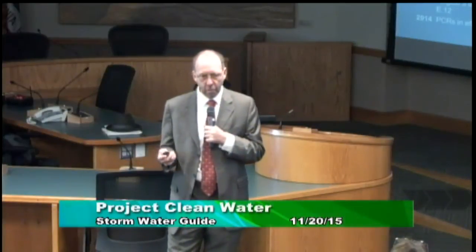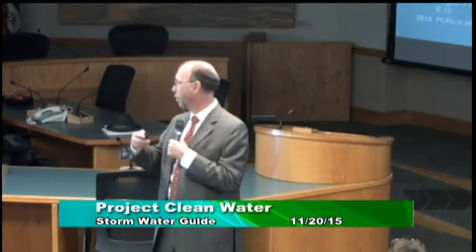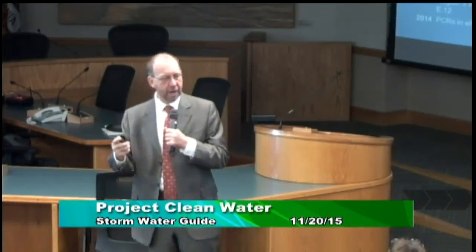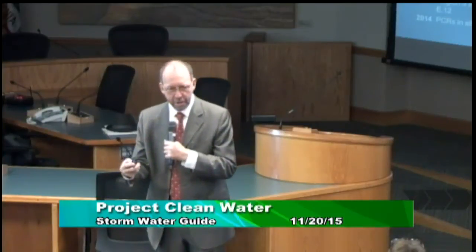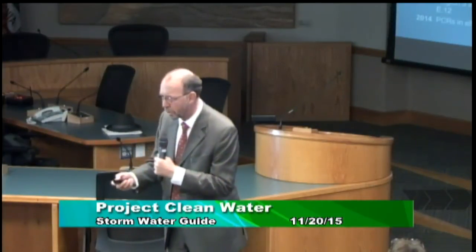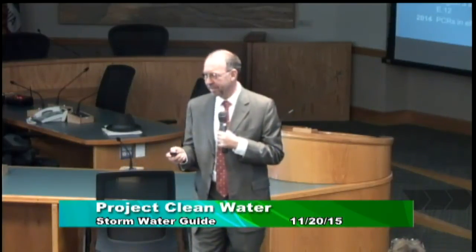But here we have to deal with much larger sizing factors. And just as a rule of thumb, when I do all my design work and explanation of how you translate this into a good urban design, 4% is my reference point because it works really well. Here, it's more like 7-8%, and it's a lot harder to do. And even at 7 and 8%, you still end up with the problems of having to have pretty deep excavations in order to provide the required amount of storage.